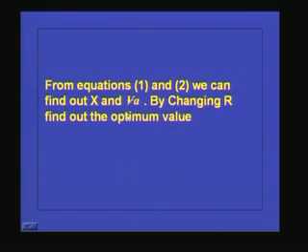But we know that the recirculation ratio can be changed from 25 to 30%. So by putting in different R values, we will get a series of curves. From that we can find out the optimum value. So this is one way of designing the activated sludge process.